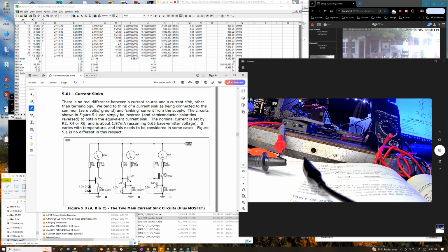But eventually it'll reach a point where it's reached that diode voltage drop across that resistor. When it does, it'll start altering its voltage. It'll start increasing or decreasing its voltage in an attempt to starve Q2 of current, because Q2, when the thing is first turning on, does start to conduct current through it, just because it's got a base current and it's doing its transistor thing, trying to drive a current through your load. Now, if you don't have a load connected, it's just going to see the diode, right? But still, the same thing's going to happen. It's still going to start starving this transistor of its voltage in order to try to reduce current.